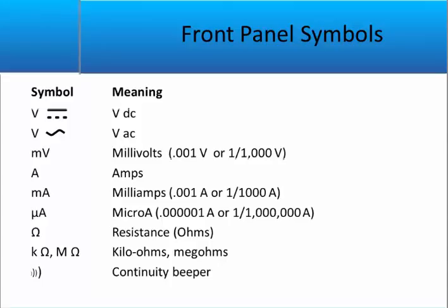So it's basically within resistance mode, but if you do have a short circuit, it will actually create a noise, generally a buzzer or a beep, when you have no or minimal resistance, and it is there mainly to be used for something like checking the continuity of a cable.